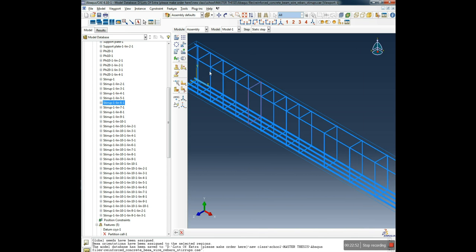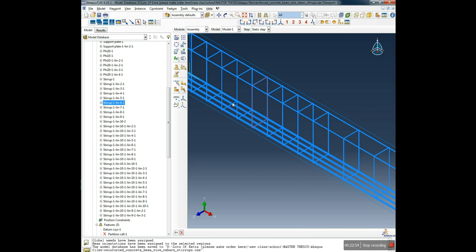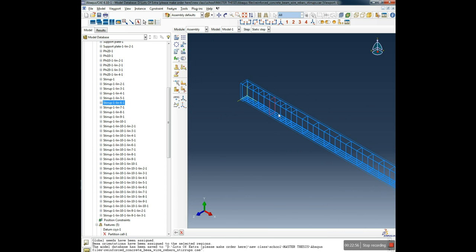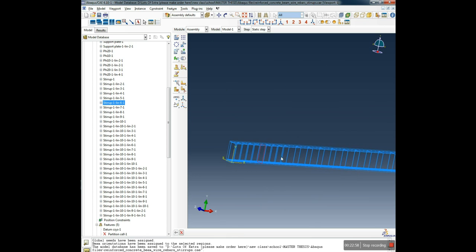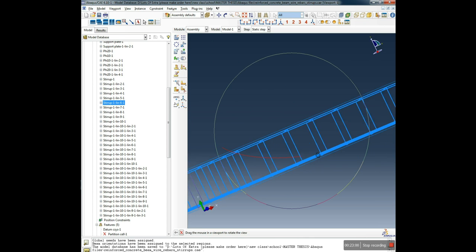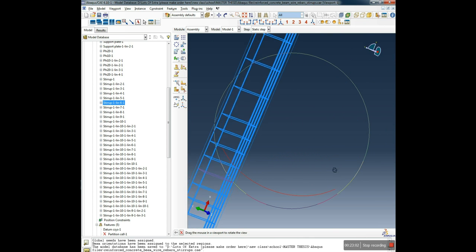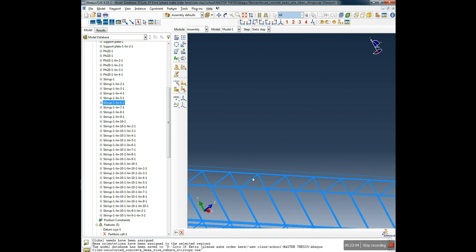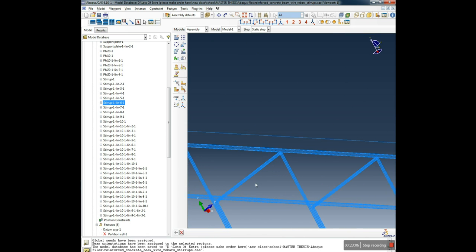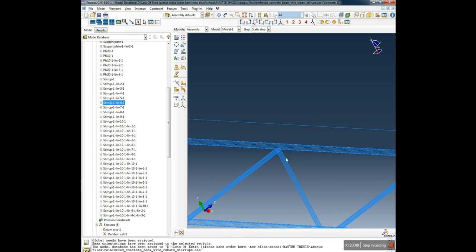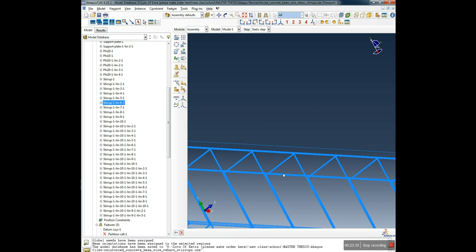You see, it's very good to check the beam render, so you know that you have done something wrong, like we know right now. Yeah, so it's clear that they are on top. So the longitudinal reinforcement is on top of the stirrup, so we calculated their length wrong.